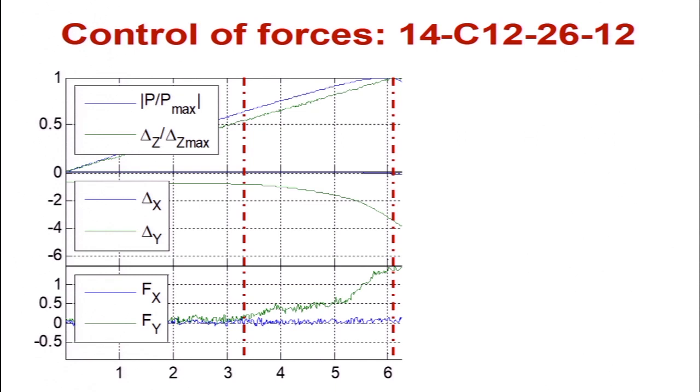And the reason I'm showing you that is because, in fact, this testing machine was simulating a fixed base condition and a pinned end condition at the top. And so ideally, these forces down here should have been 0. They are not, but they're very small. These are in kips, and so we might have been getting half to 1 kip of lateral force, while we were imposing perhaps 1,000 kips of vertical force.